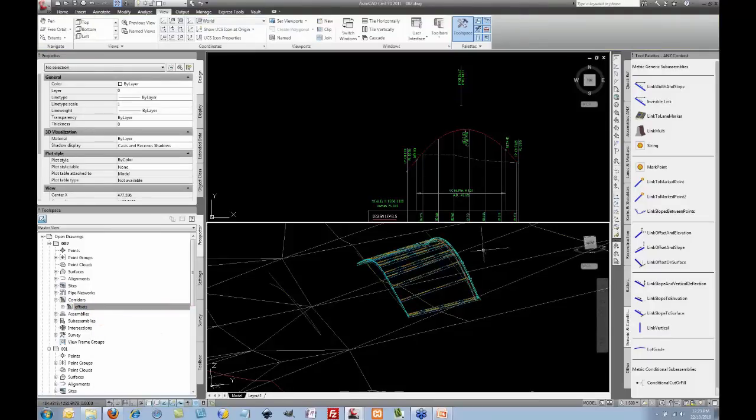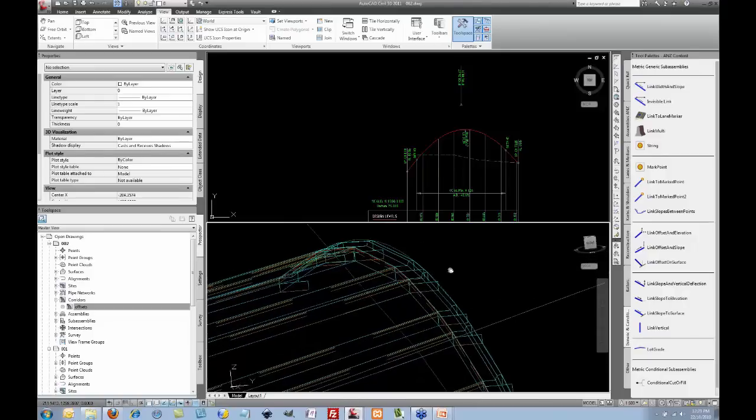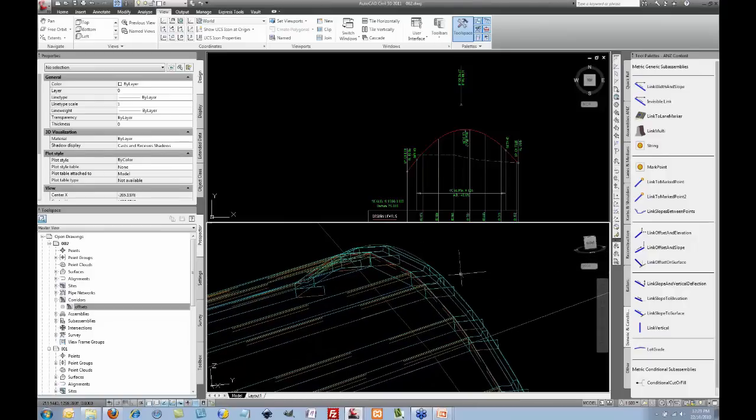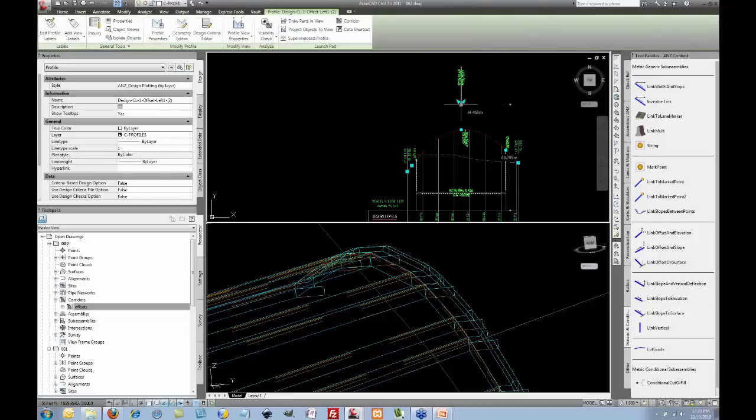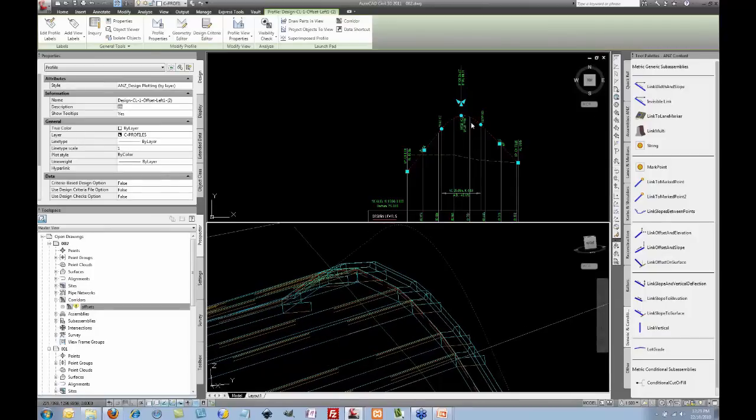Very simple. Now, let me just zoom in and show what's different about this, because you could do a very similar thing just using the edge of the road, but in this case, we're not playing with the edge of bitumen, we're playing with the back of the curb. So I'll do it once more, and the dotted green line should show us what's happening. So I'll raise this up some more, I'll drag it along. Oh, sorry, my curve radius is too great, I can't do that. Okay, now let me adjust that one more little bit.